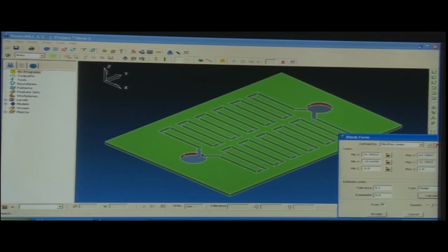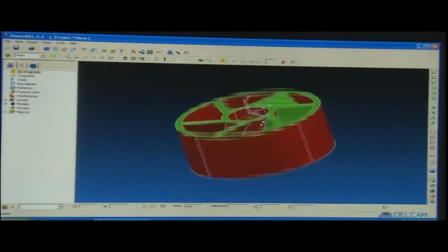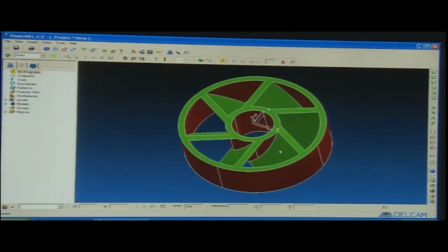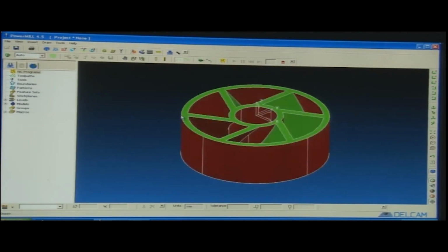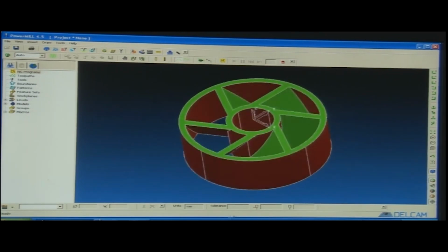There are some jobs in which it is difficult to find corners. For example, in this we cannot find any corners. This job is also a circular job. This can be manufactured in the machining center, that is the milling machine, as well, and also on the lathe machine. But the reference point for this job has to be the center.